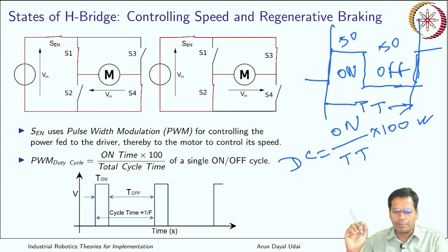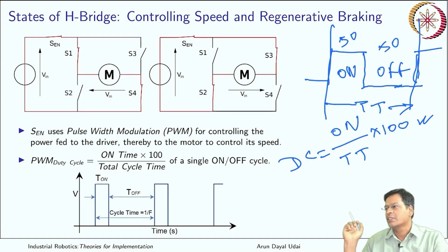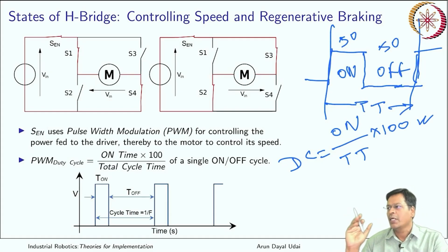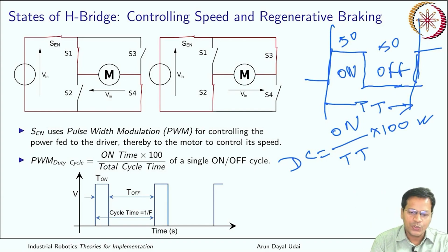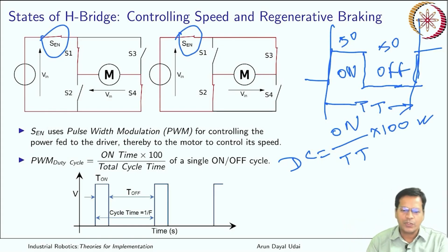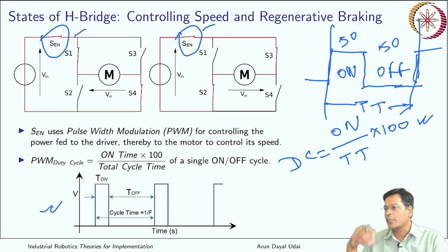This is known as a PWM waveform, or pulse width modulation. This is used to control the effective power that goes into your motor, and that can finally control the speed. And how is that done? You already know you have a switch over here. Whatever direction your motor is rotating, you can have a transistor switch, which we feed with this type of control signal.